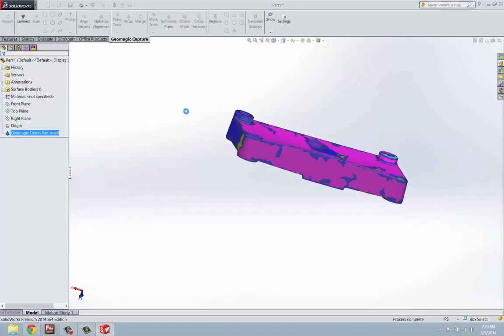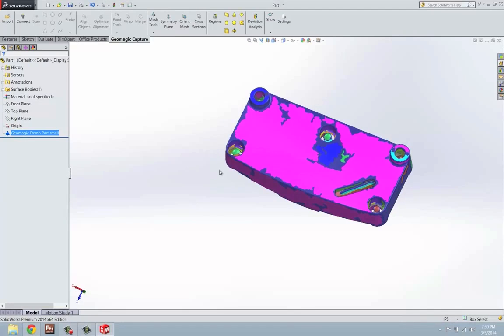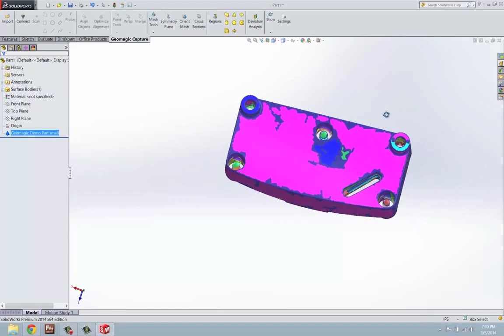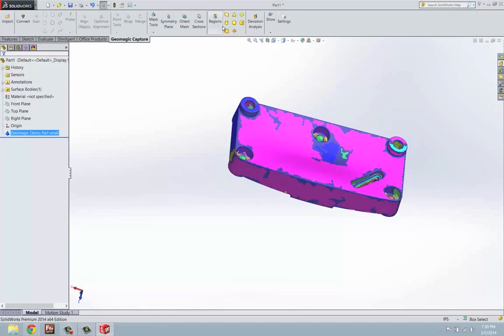So once this is done, the next step we're going to go through is our Extrusion Wizard. Our Extrusion Wizard is going to allow us to take this basic shape, and just like in SolidWorks, you start out with your basic shape, do some smart dimensioning or whatnot, and then extrude out your full model, right? So we're going to do the same process here. We're just using a wizard to actually help us along and get started with this mesh.